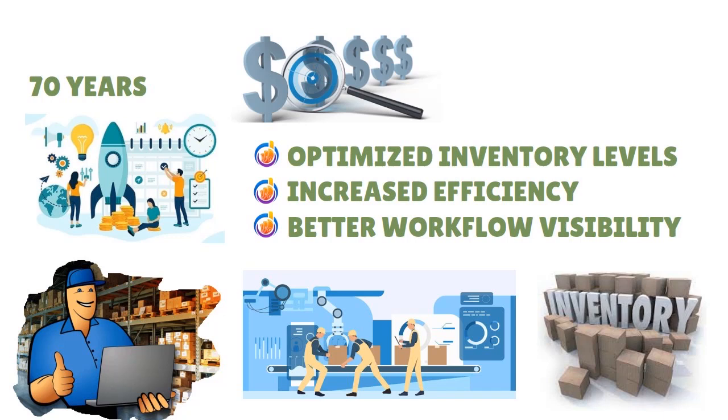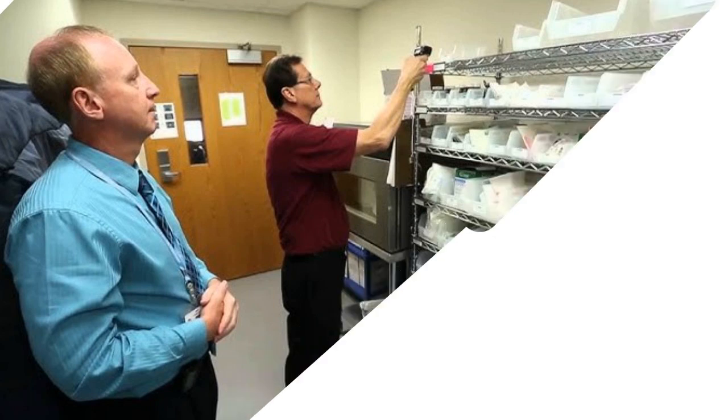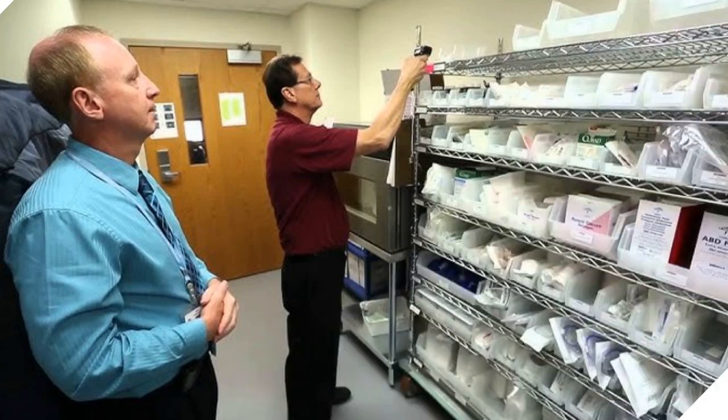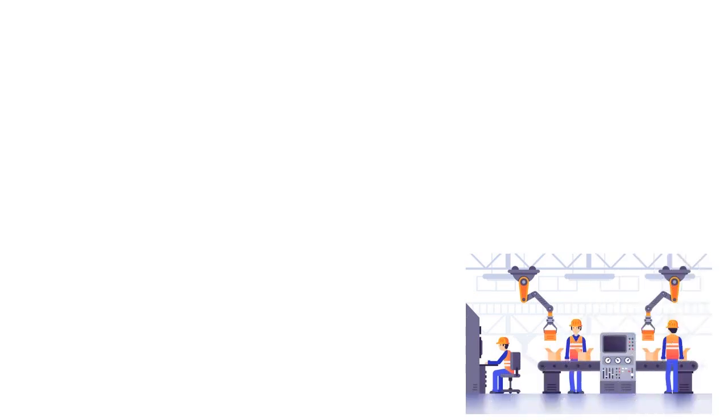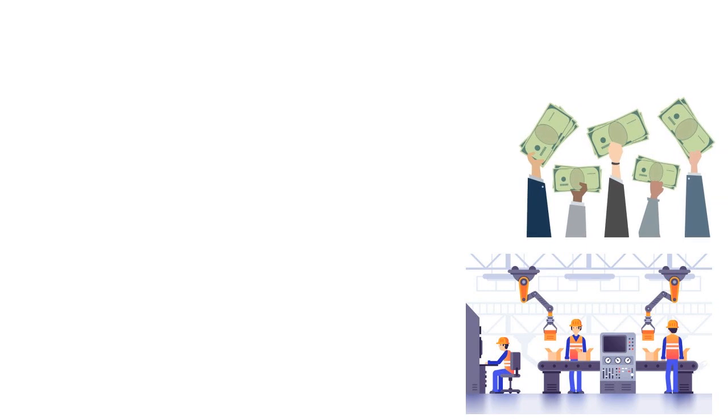So what happens here is that when you use the Kanban system, you are able to boost efficiency either directly or indirectly because the system focuses on producing for customer demand. So demand is driving production. Customers are driving production, and that's what happened with Toyota. That's what they did back in the 50s. So production and withdrawal Kanban cards keep parts or inventory items moving as needed. So this increased efficiency translates to shorter lead times, cost savings, and increased adaptability.